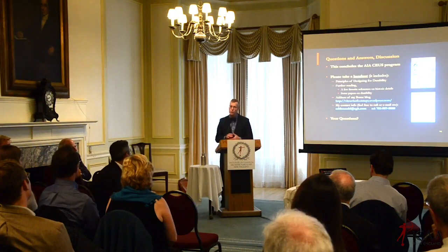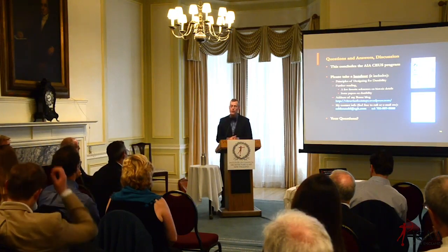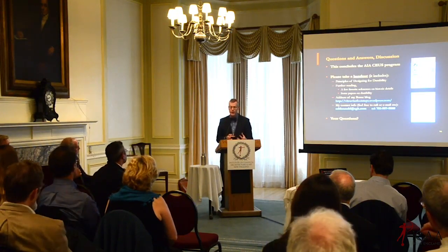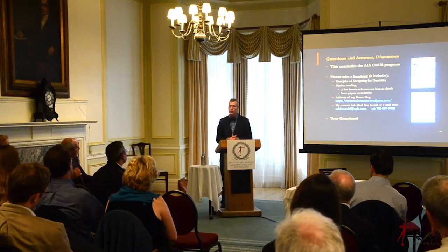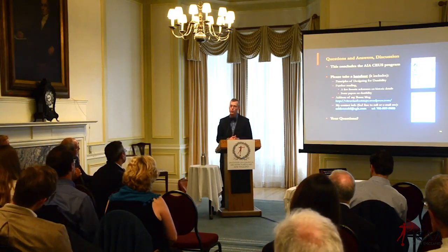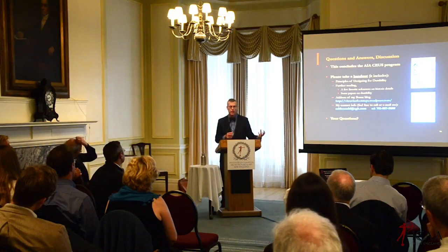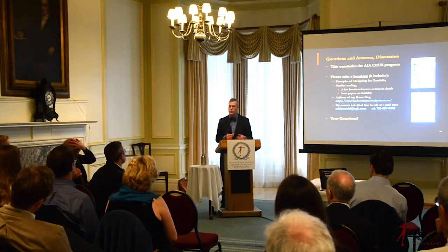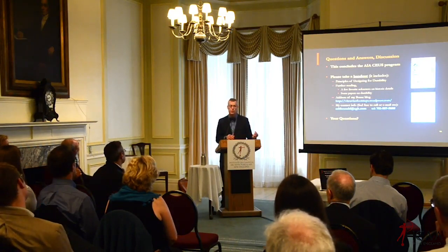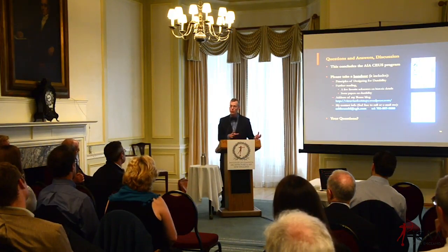Yeah, so they did use volcanic ash, pozzolana, and that's what imparts what we would call the naturally hydraulic quality. A lot of times when you look at a 1600s, 1700s, or early 1800s building in the U.S., you have a pure lime mortar.